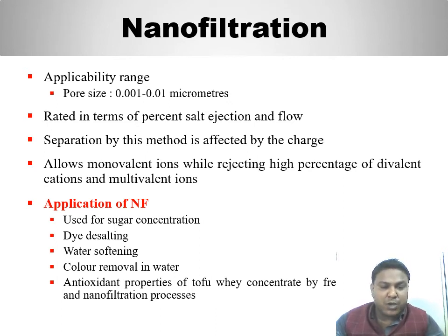Nanofiltration separates food components in a region between reverse osmosis and ultrafiltration. As said earlier, the typical particle size used for nanofiltration is about 0.001 to 0.01 micrometer, and operating pressure is in the range of 20 to 30 bar. Separation by nanofiltration is affected generally by the charge.